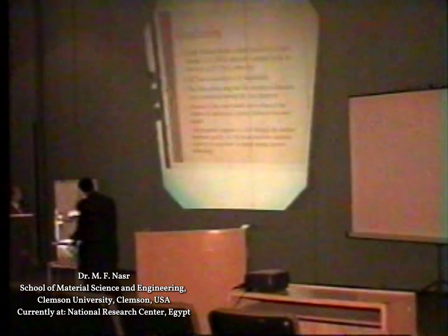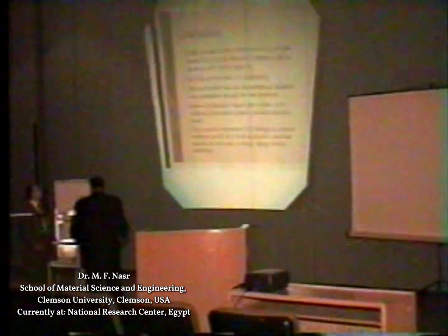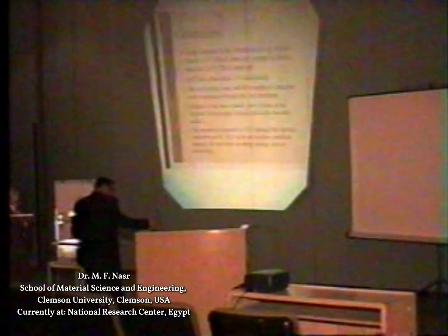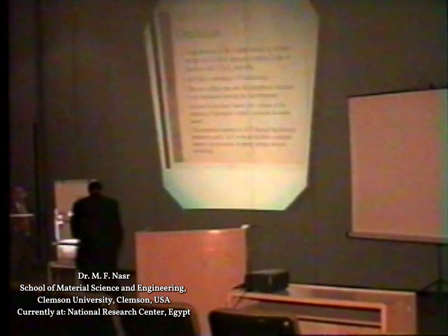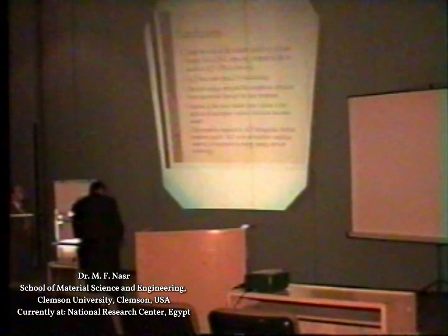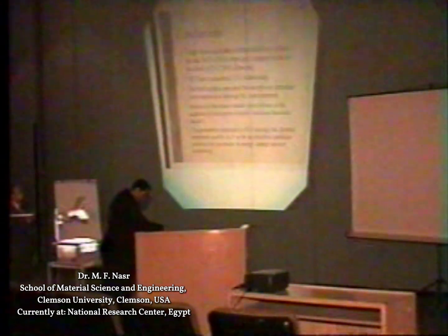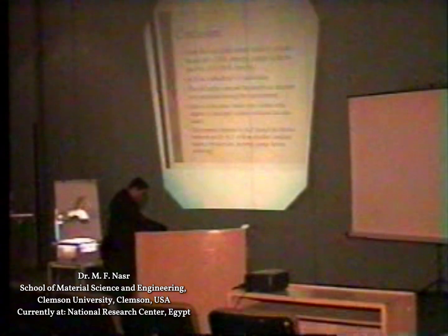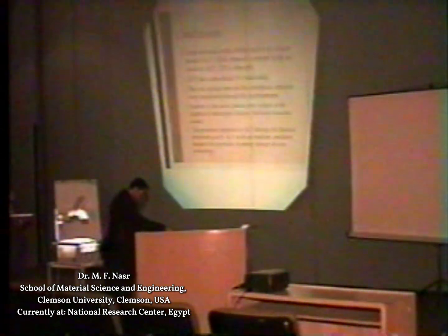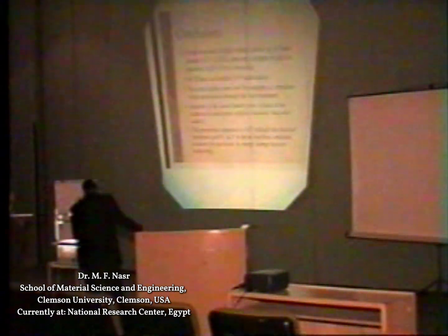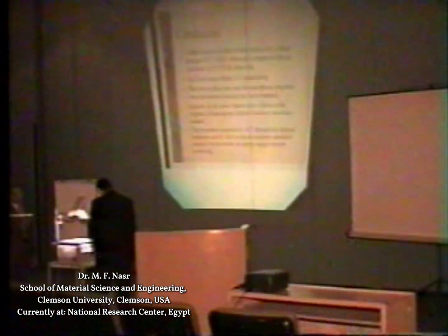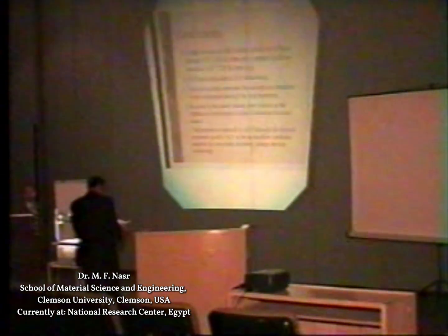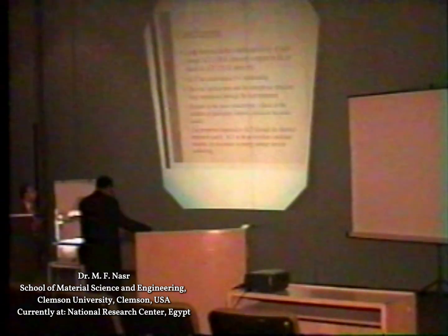Now, finally, the conclusion. We get a large decrease in the volume resistivity just with the heat treatment. In our subsequent papers, we did some type of composite material with the same ACF. But here, just with the ACF and heat treatment, we get a decrease in the resistivity from 720 to 130 just with heat treatment at 900 degrees for 30 minutes.